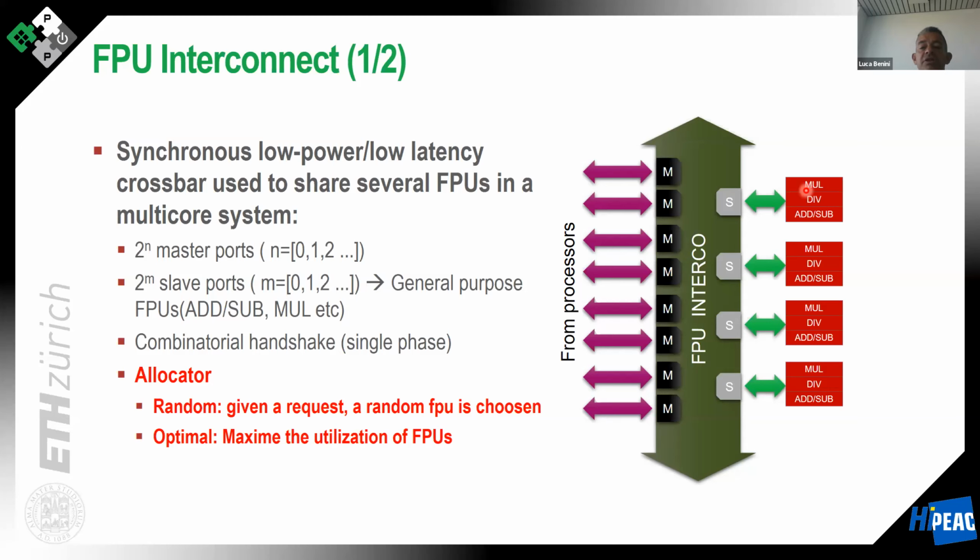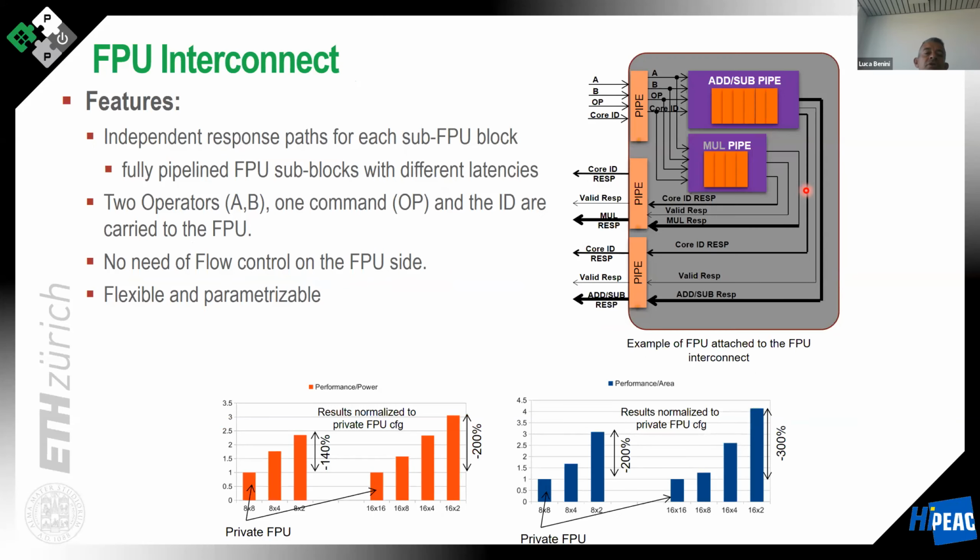So these three interconnects have a different input-output behavior because they have a different mapping logic and arbitration logic, but they provide similar services. So they provide an N-to-M connectivity that emulates a multi-ported access. So, for example, to show an example of the last one that is a bit different from a memory network, this is a technique that we use to share the large floating point unit.